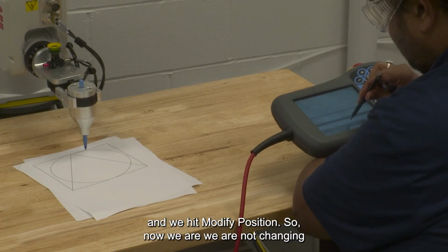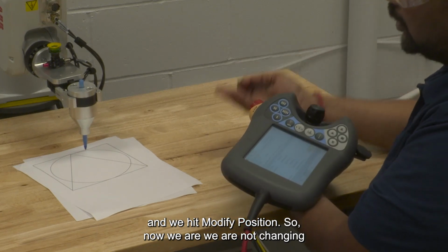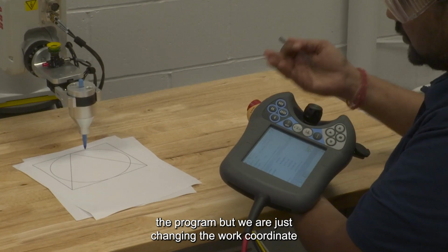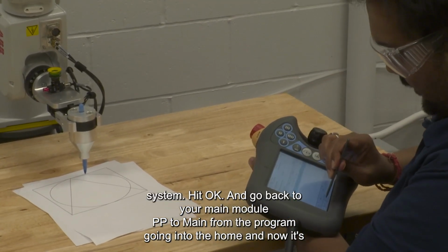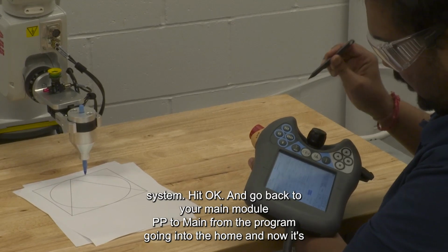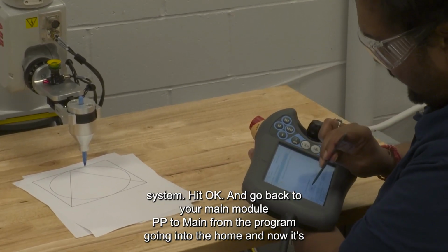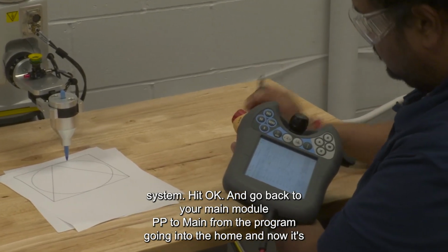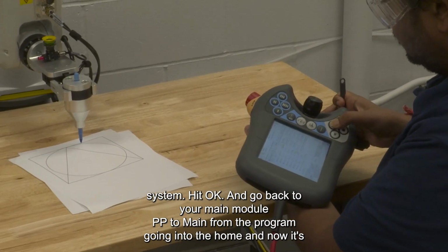And we hit modify position. So, now we are not changing the program, but we are just changing the work coordinate system. Hit OK and go back to your main module, PP to main, run the program.